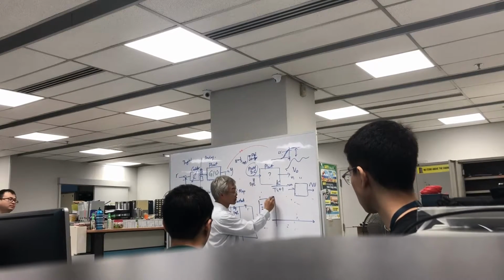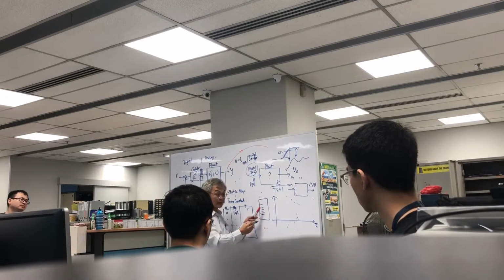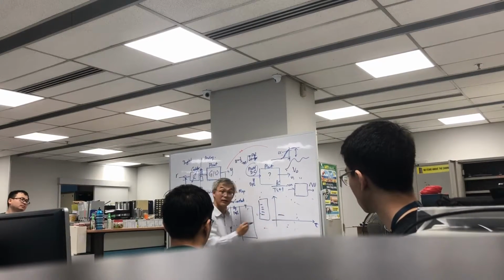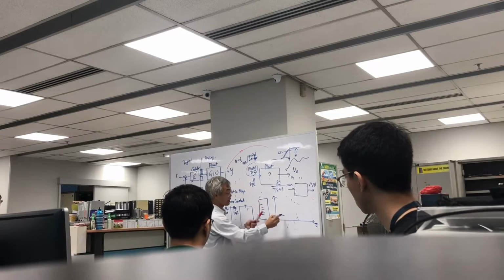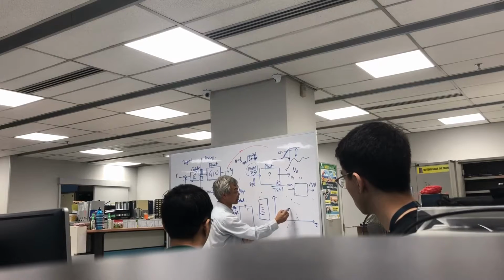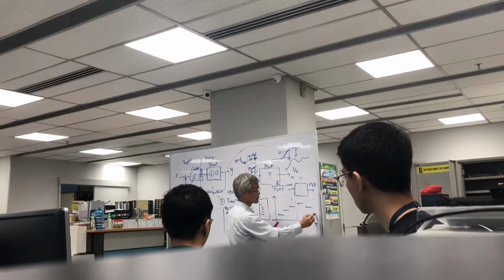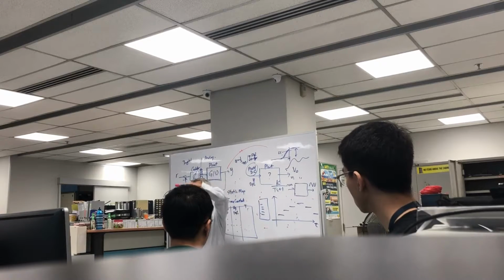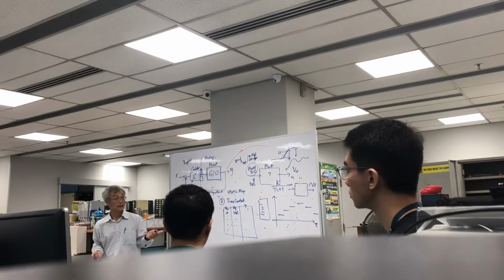So you imagine your scope, this is your time. The scope, you monitor the output. Alright? So the first round, 10%, the output will be here. Let's say you hold it for 1 second. And then the second round, 20%, the output will be here. And then if you write a program, then just cycle through. Step up and step down. You'll see this. Okay? So by this one look, it tells you quite a lot of things.